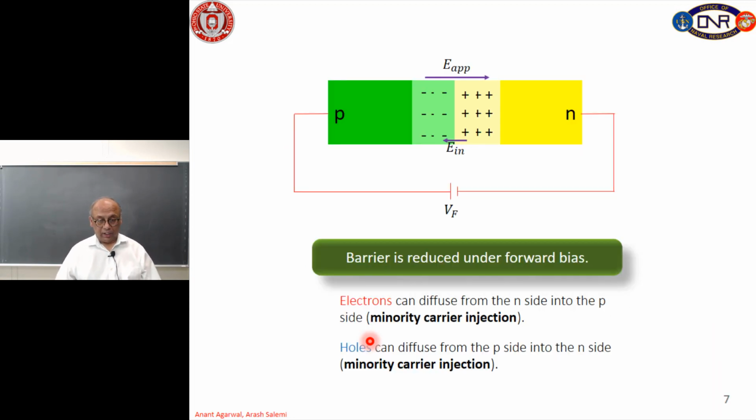All right. Now, let us consider the forward biased PN junction. What we have done is we have taken a battery or a voltage source, and we have applied positive voltage to the P side and negative voltage to the N side, and this is called the forward voltage. And notice that the applied voltage opposes the built-in voltage. So, the net voltage across this junction will be reduced by the applied voltage, right. So, now once we reduce the built-in voltage across this junction,